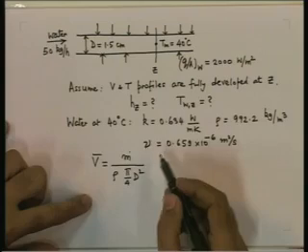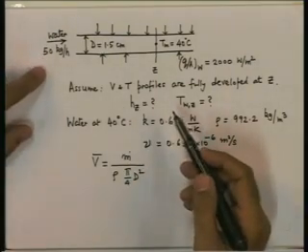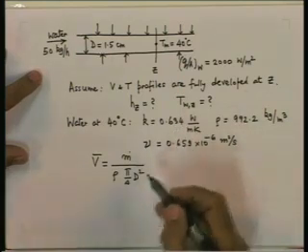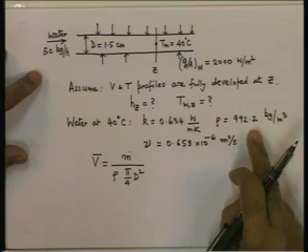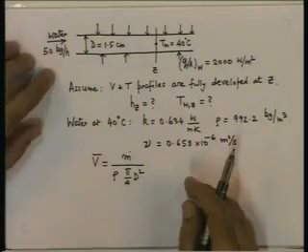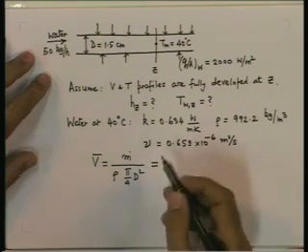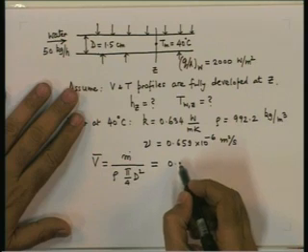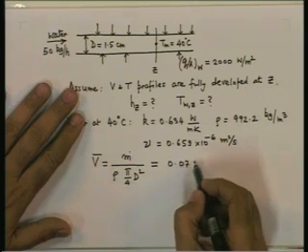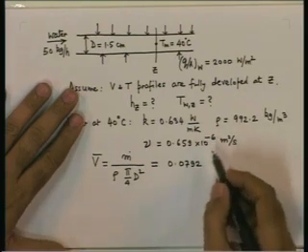If you substitute the flow rate 50 divided by 3600 kilograms per second, density as determined, and the diameter of 0.015 meter, you will get this velocity to be 0.0792, just about 8 centimeters per second.